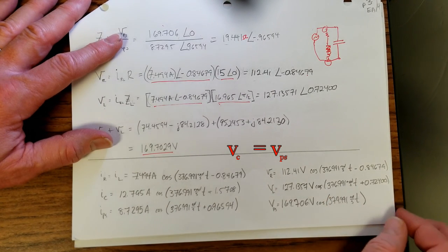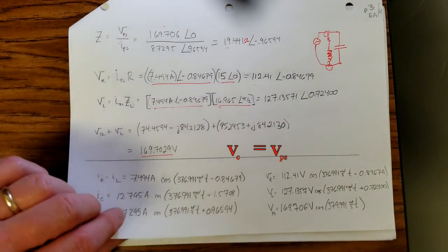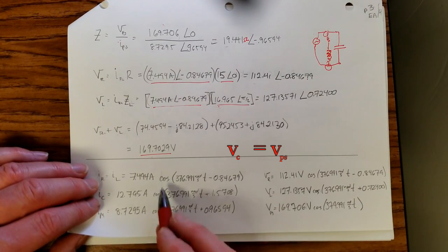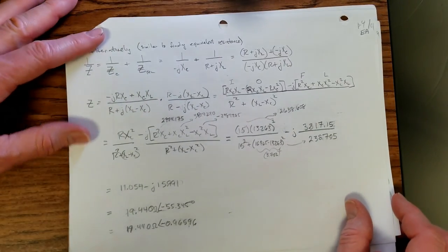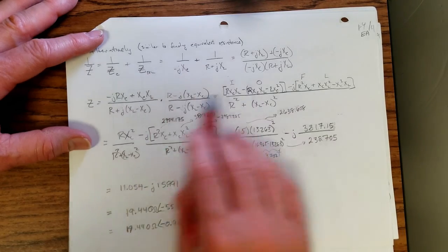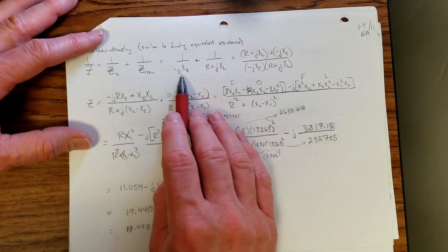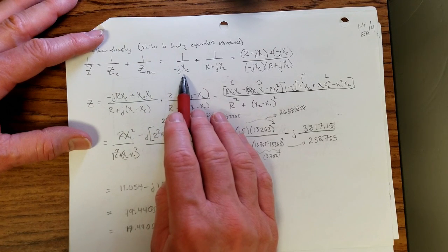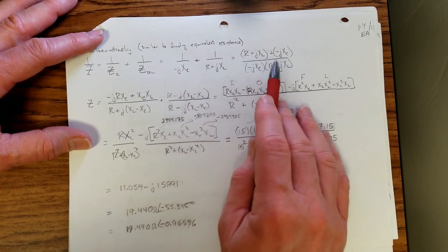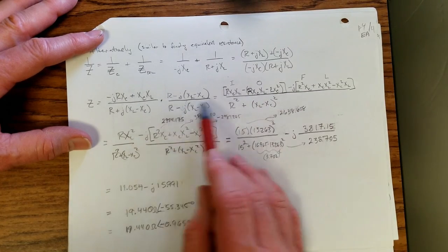And that is just a whole lot easier than what we had just done in the other video, or what you will see in the other video. And so now I put in the full form where I've got the actual omega values in and the cosine. Alternatively, we could have found the total impedance by 1 over Z sub C plus 1 over Z sub RL. Now, it depends on what point you want to put in numbers, but working out in terms of letters, I've got 1 over Z sub C, 1 over Z sub RL, and then I go ahead and get a common denominator, add them, and so the total impedance is just the reciprocal of that.